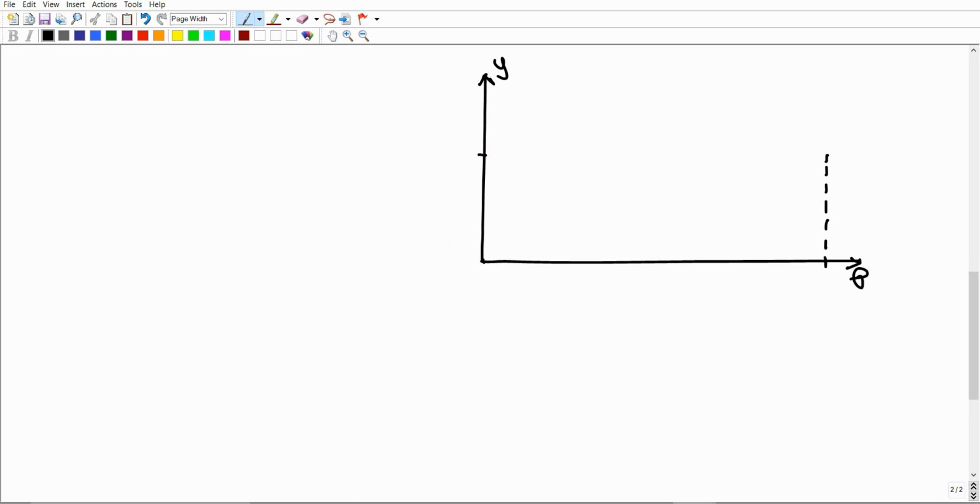Then your objective is just to measure over the y-axis the total lift, which is already given to us as 50 millimeters, equivalent to 5 centimeters. I'm gonna work at a 1 to 1 scale, so I'm gonna measure the 5 centimeters, then mark a point. Then from this point, I'm just gonna draw a horizontal line to close the dashed rectangular shape, as already shown here. Make sense? So you could consider that this is the drawing area, this is the drawing zone.